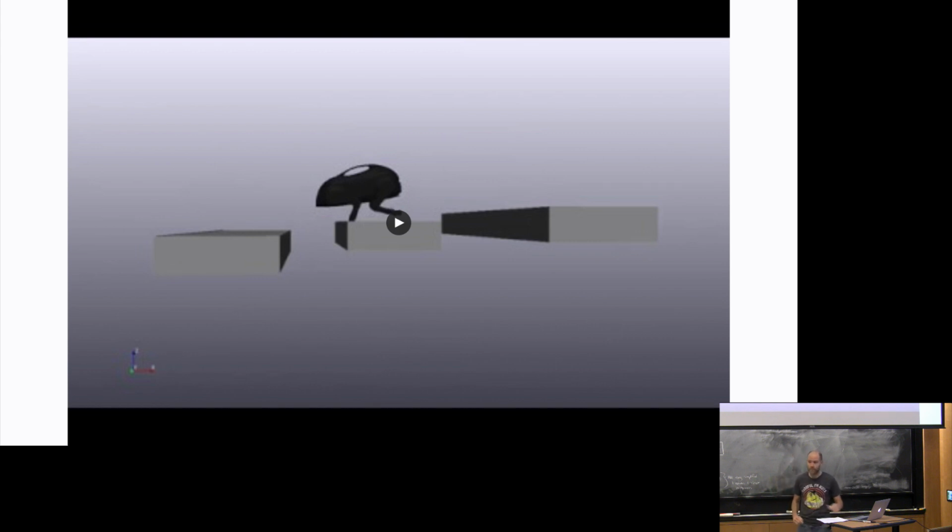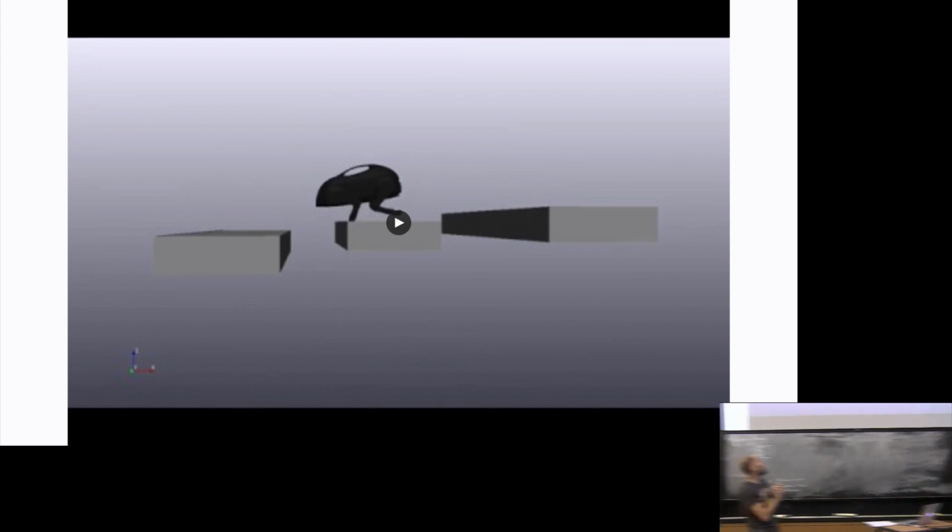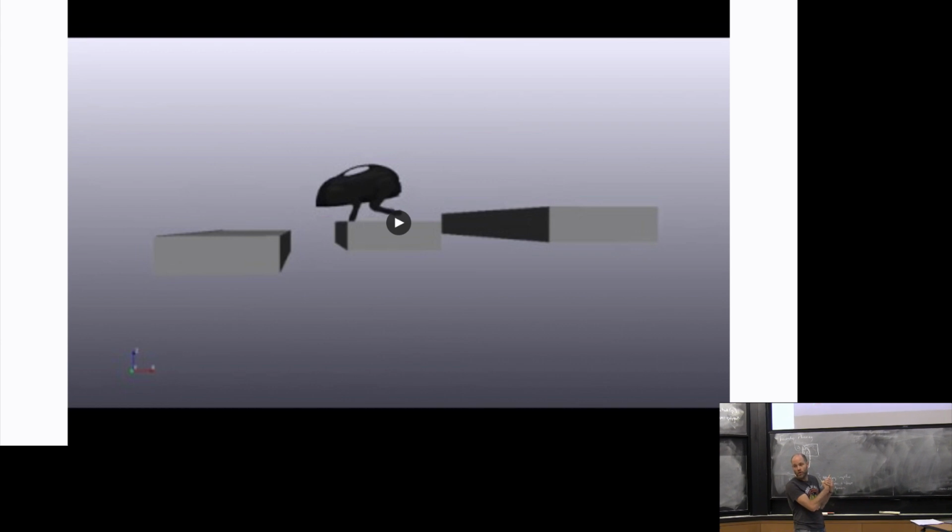Yes, please. Is this still position control or is this force control? This is a trajectory that's played back; it does not need to know the forces at the joints. I think in simulation we often assumed we had torque there, but I believe that as long as you're able to regulate your center of mass trajectory, it could be done with a position-controlled robot.